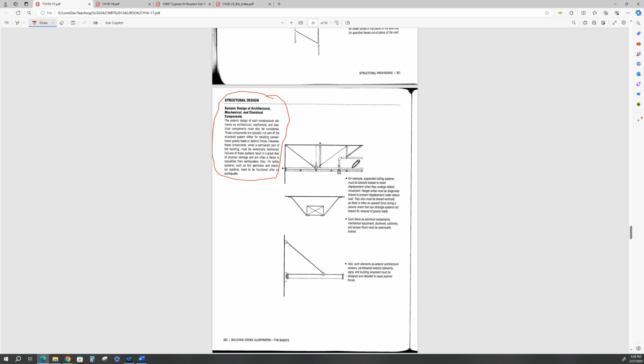If the building's stretching the pipe, it'll break the joints loose. Your suspended ceilings, just like in fire, we talked about the support wires. Well, here we have some lateral supports to keep the suspended ceiling so that it can ride that frequency wave.